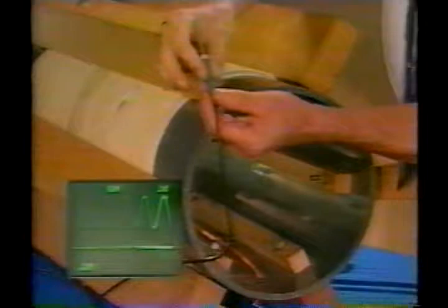The magnetic field along the z-axis can be found by simple integration of the Biot-Savart law. The essentially phi-directed current along the entire winding generates a z-directed magnetic field along the axis of the cylinder. This is the on-axis distribution of the axial field intensity for our solenoid, which has a length-to-diameter ratio of 2.58. We can compare the prediction of this formula to our experiment here at the end of the solenoid. Biot-Savart predicts a flux density of about half of the 2.5 Gauss in the interior.